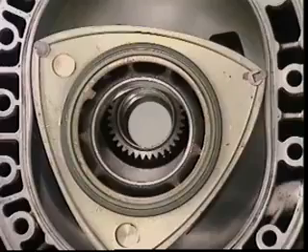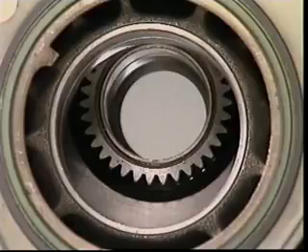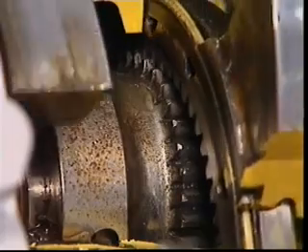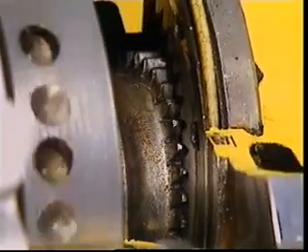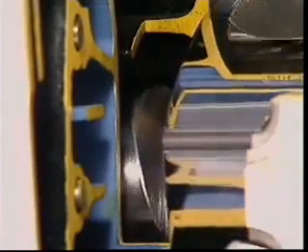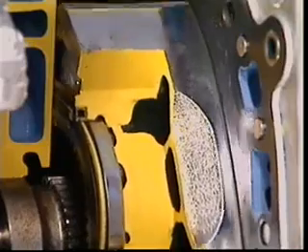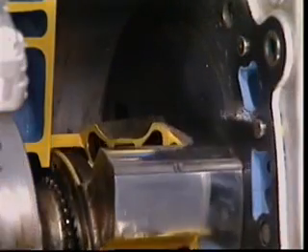An internal gear in each rotor meshes with a corresponding stationary gear in the front housing and rear housings. When combustion occurs, the meshing of the teeth forces the rotor to walk around the stationary gear. This combines with the eccentric shaft to make the rotor follow the curved surface of the housing, and it gives the rotor planetary motion.